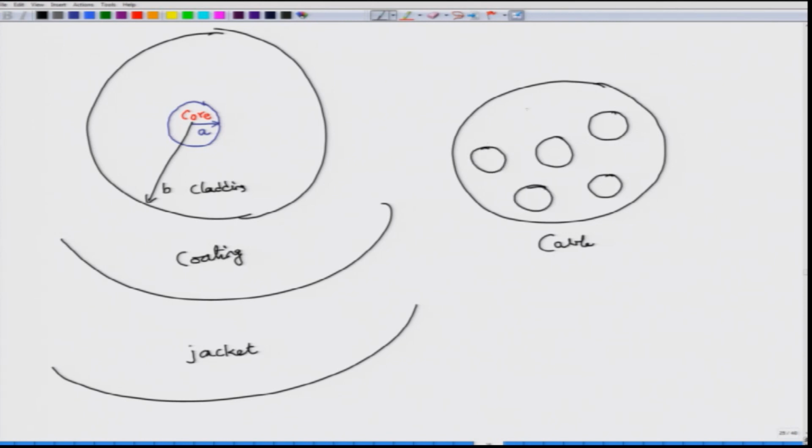We are going to look at optical cables later on, but each of those circles that I have drawn here are not really cores, they are actually what are called loose tubes. Okay. So, inside this loose tube you have individual fibers. So, these are the individual fibers. Here these fibers just have a core and a cladding. Okay. They do not normally go with the coating, and these loose tubes are also differently colored for visual inspection later on, but this is how an optical fiber cable looks.